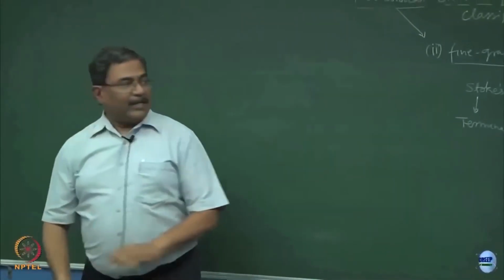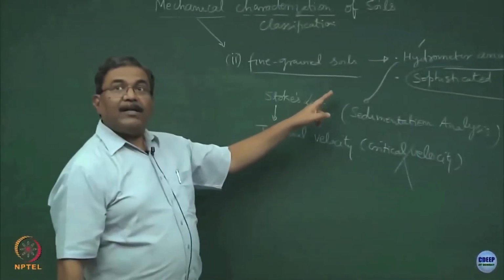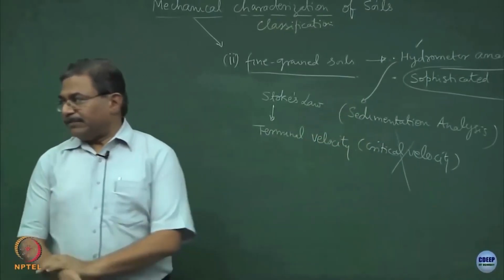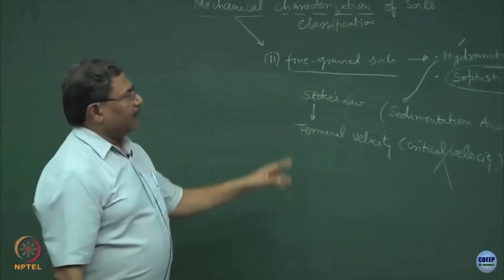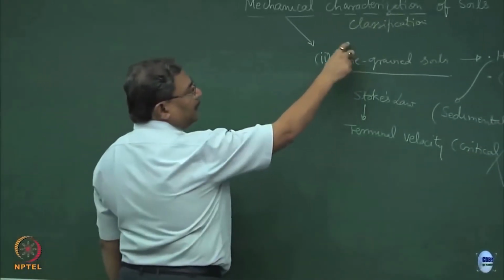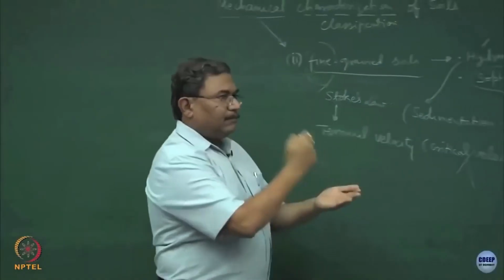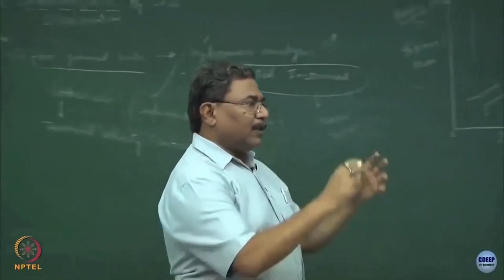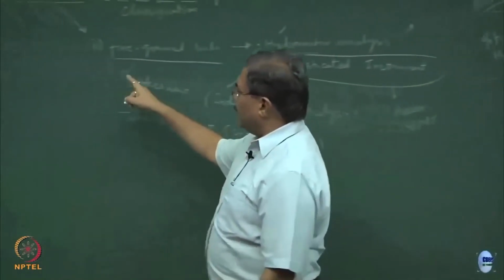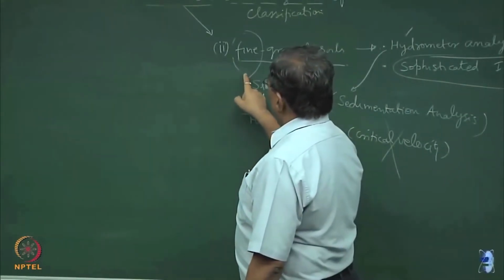Fine grained soils, the moment you put them in the oven at high temperature, their activity is lost. So, you should not have done this mistake; air dry them. So, we will put a condition over here. Remember, in coarse grained material we said take the soil, pulverize it and put it in the oven. In fine grained material we should not do oven drying, we should do air drying.